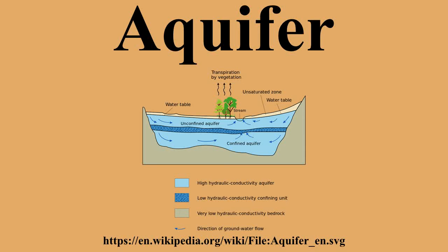Saturated versus unsaturated: groundwater can be found at nearly every point in the Earth's shallow subsurface to some degree. Although aquifers do not necessarily contain fresh water, the Earth's crust can be divided into two regions: the saturated zone or phreatic zone, where all available spaces are filled with water, and the unsaturated zone, where there are still pockets of air that contain some water, but can be filled with more water.